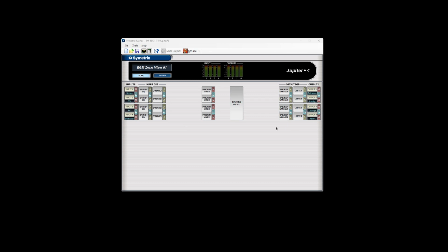For our zone source and volume control, there are 3 main sections we'll focus on. Outputs, which are the physical analog outputs that are the zones in the building. Routing matrix, which will determine which zones get which priority mixer submix. And priority mixers, which will equate to our zones and which sources go to the physical outputs.